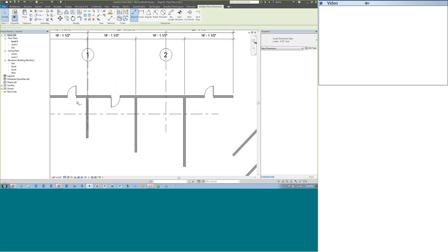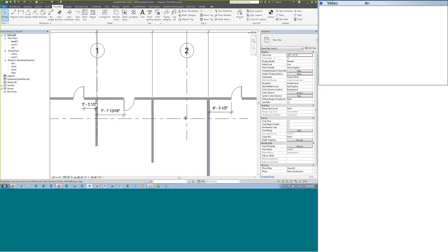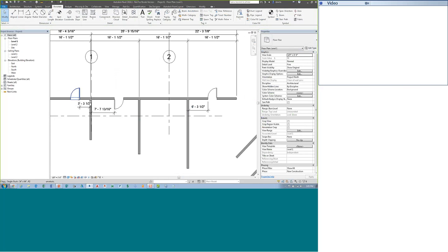Okay, I'll throw in a dimension. Oh, by the way, DI is a keyboard shortcut for dimensioning. And you can actually click the tab key to force it to look at another entity when it's dimensioning, like so. And so we have a design situation where the client says, I want all the doors to be 8 inches off the corner if they're next to a junction like this.